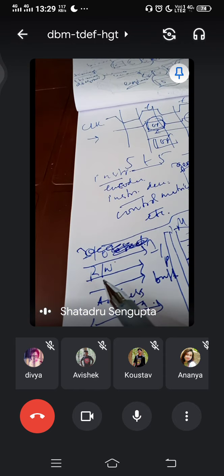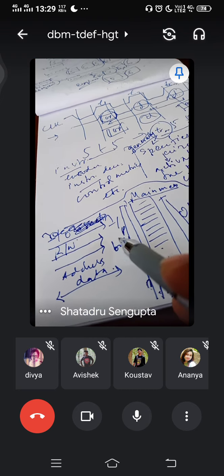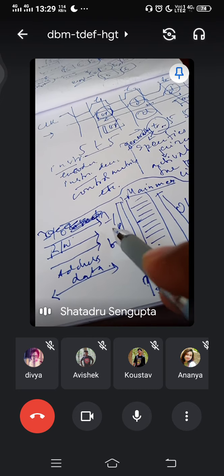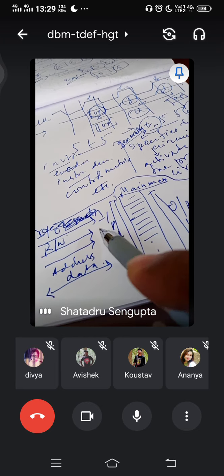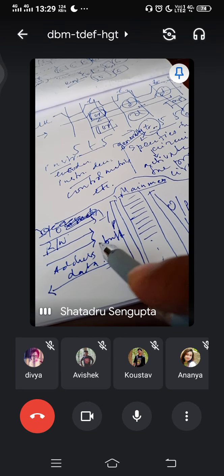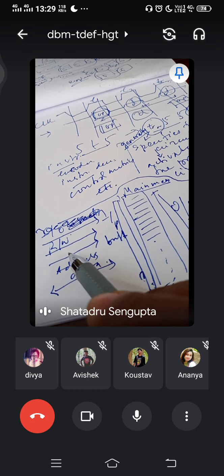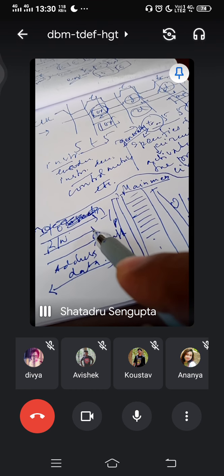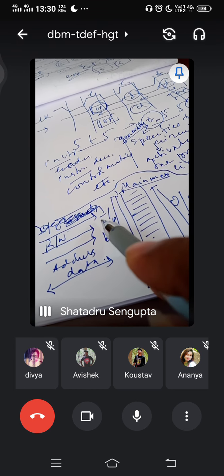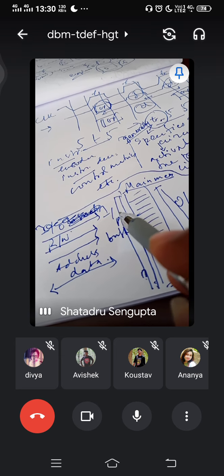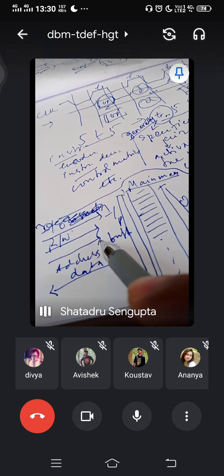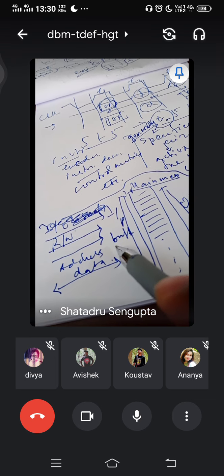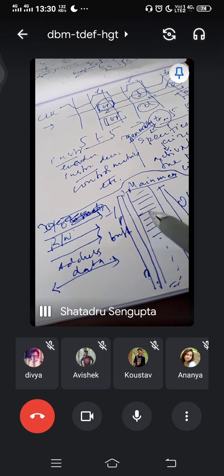So it sends out the read write signal, and according to whether it's read or write, if it's read, the output buffer is on. If it's write, the input buffer is on. Then the address bus follows through with the address. So for the read write signal, there is a selection logic here that either activates the output or activates the input. For the address bus, there is an address decoder which selects only one line at a time.